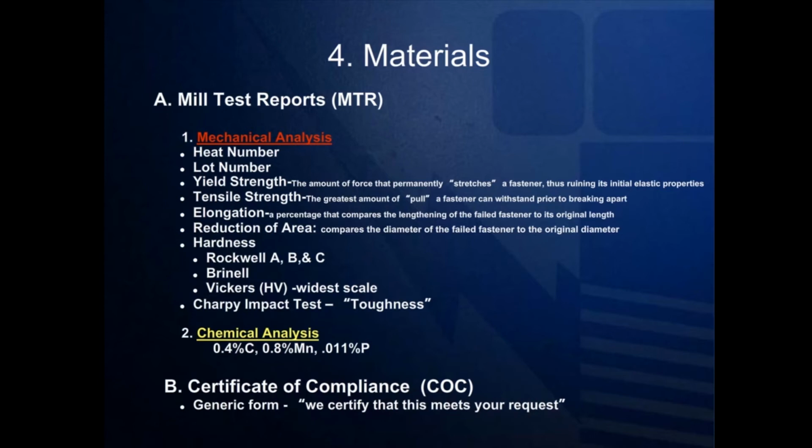Another common measurement in an MTR is hardness. Similar to temperature having different units like Fahrenheit and Celsius, there are different units of hardness which include Rockwell, Brinell, and Vickers. There is also a toughness test called a Charpy impact test, in which a pendulum is crashed into the material. By measuring the dent, one can conclude the material's toughness, thus the amount of energy needed to fracture a material, which is directly linked to its brittleness.